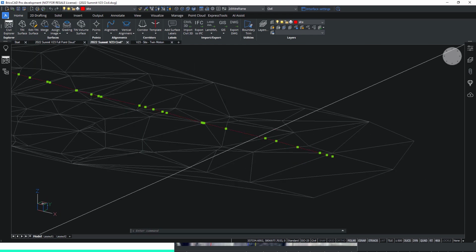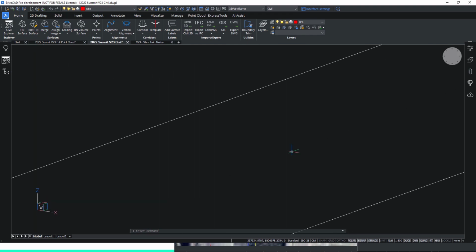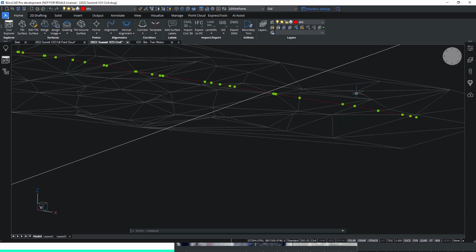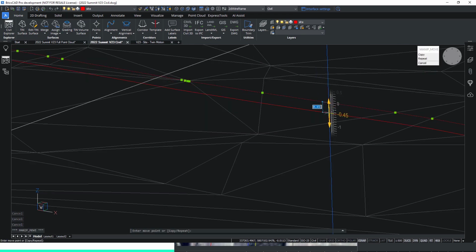What I'll now do is use the manipulator. Let's hold over this and lower this by the depth that we read from our attributes, which is 1.2. Let's type in 1.2 here.